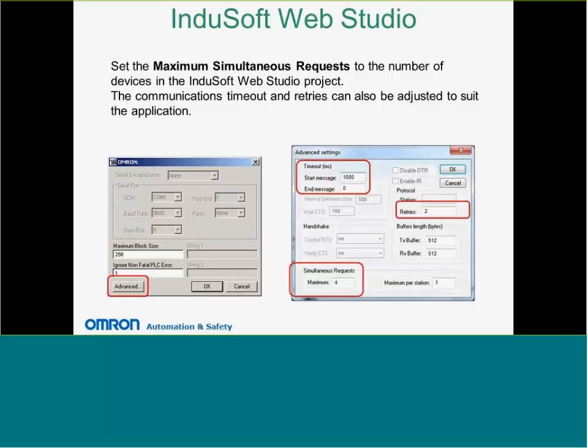So it's not a round robin of all of the PLCs as far as reading data. You've got 4 asynchronous communication pathways open, 1 to each of your PLCs. So it really optimizes and makes your communications very efficient.